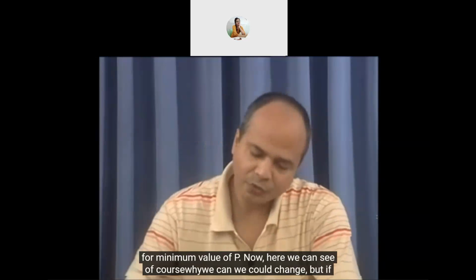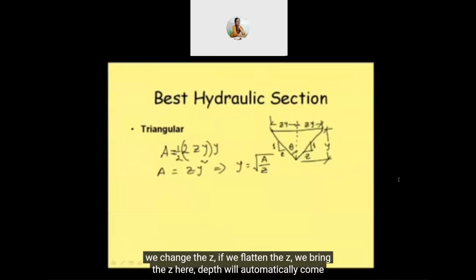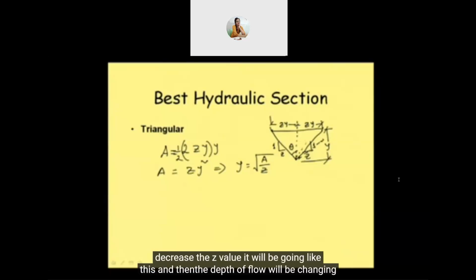Now here we can see, of course, y we could change, but if we change the z, if we flatten the z, depth will automatically come down, or the perimeter. So for a given area, if we change the z value, the depth will change. If we increase the z value, it will be coming like this. If we decrease the z value, it will be going like this. And then the depth of flow will be changing, and then the wetted perimeter will also be changing.